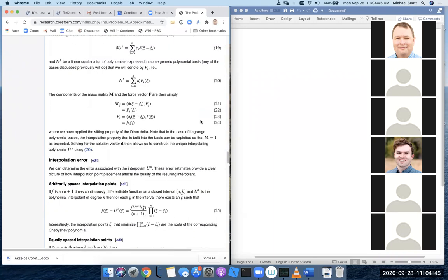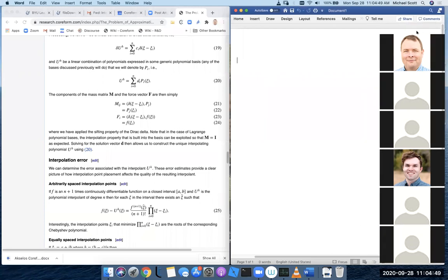Okay, what I wanted to do was talk about quadrature. If you've ever used finite elements, maybe at first glance this appears to be an esoteric topic, but it is really a big deal in finite element methods. And in fact, if you're just a user of the software, it's a big deal because you make all kinds of decisions with regards to how quadrature will be used for a given finite element run.